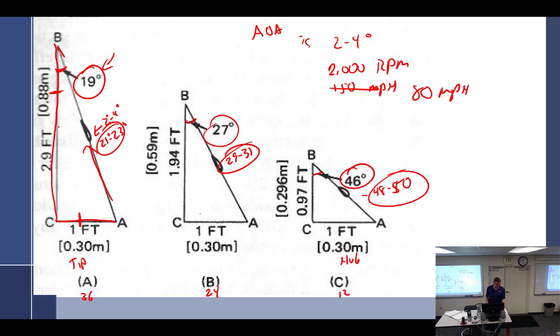So when I tested airplane engines on a test stand, we needed what was called a test club. Remember those? It's a four-bladed, fixed pitch wooden propeller. You're supposed to get one for each engine. I was thinking about the one we used for the 200 horsepower Lycomings. When you went wide open throttle, it went right up to 2,700, which is max redline, and that tells me it was absorbing 200 horsepower, because the engine put out 200 horsepower at 2,700 RPM. So the pitch was designed to go right to 2,700 and give you that.